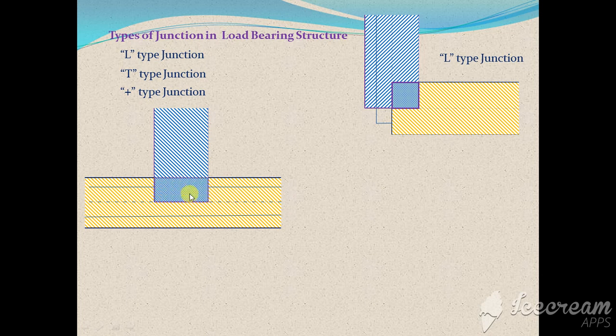But in this case, this particular shaded portion that is shown will be calculated twice, and hence we can say that half the width of that particular item is calculated more, and that's why this length of half width for the T junction is to be deducted from each T junction.